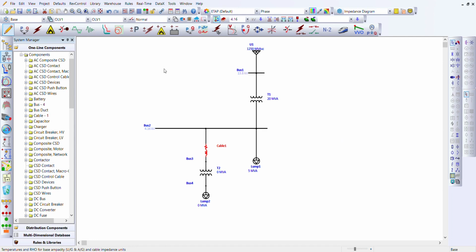This is frequency. But from the specification of the cable, we have the kV, which is this, to be 5.0. So all we have to do is keep searching until we get to 5.0. Okay, we've gotten 5.0. Now remember also it says copper. Now this is aluminium for the type.